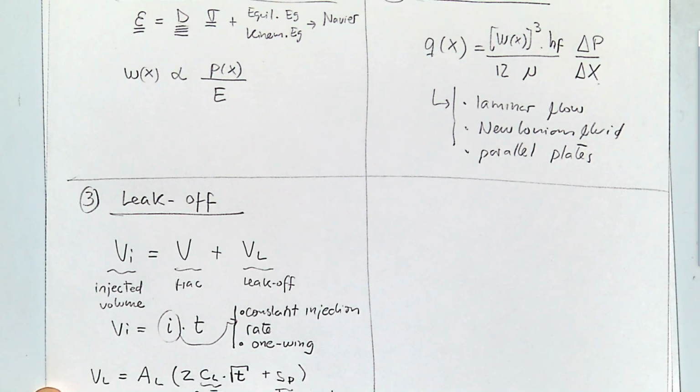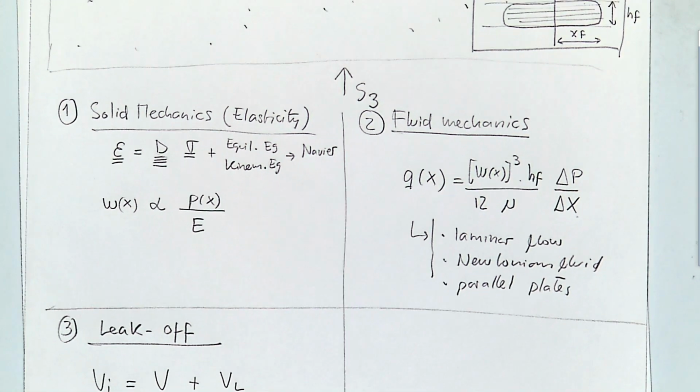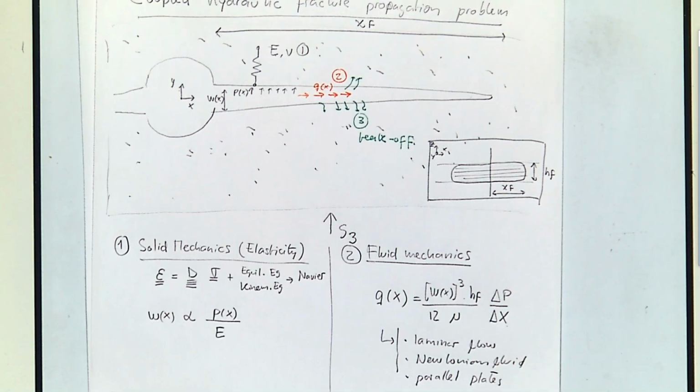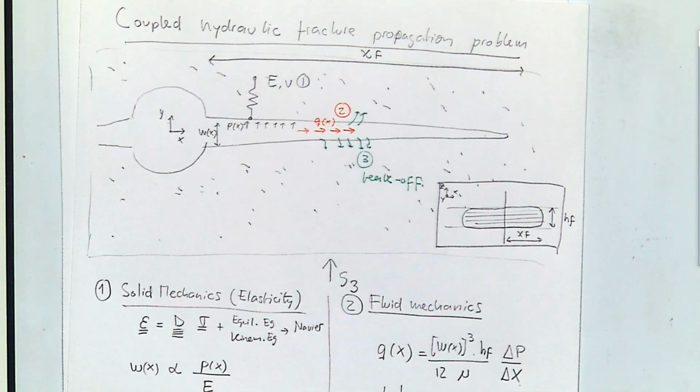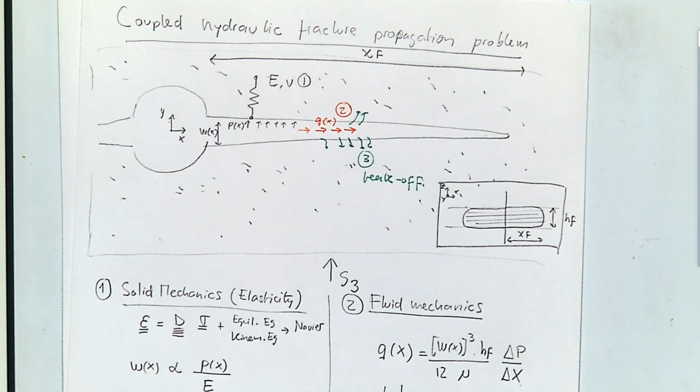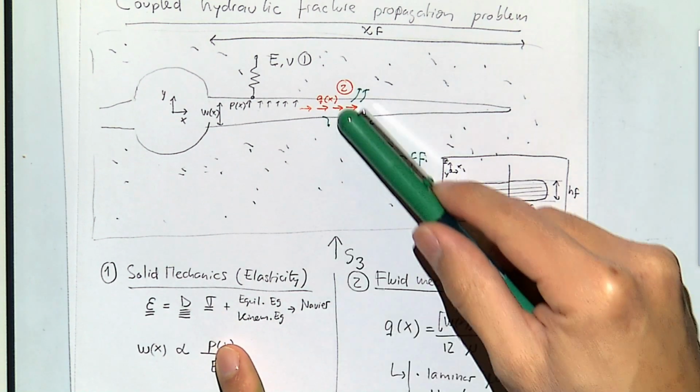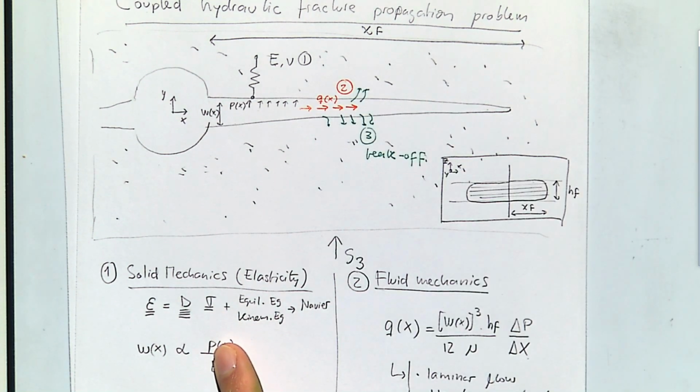Okay, so we have figured out most of the problem of fracture propagation. What are we missing here? It's also nice to think about this in terms of energy. Where do all the horsepowers that you spend on surface go into propagating the fracture? Well, some of it goes into strain energy, keeping the fracture open.